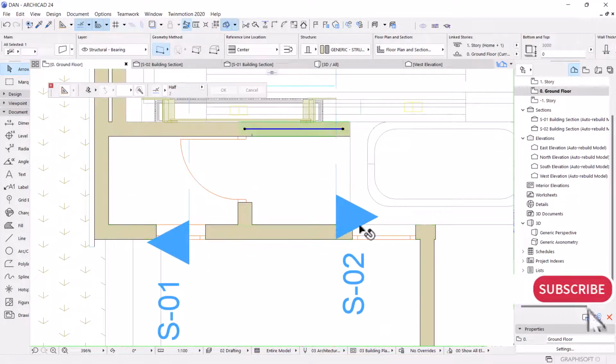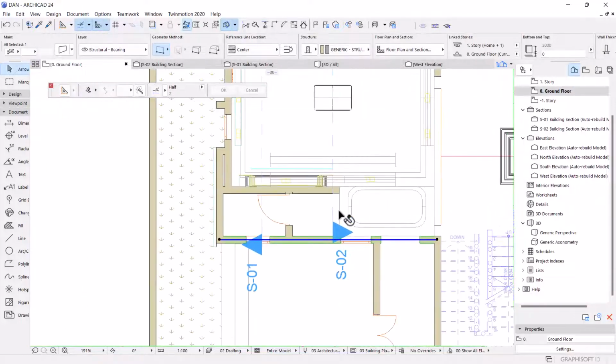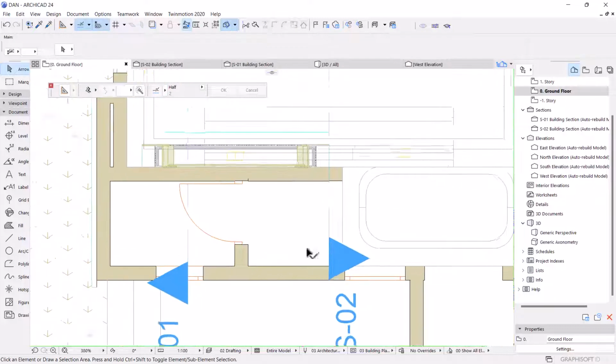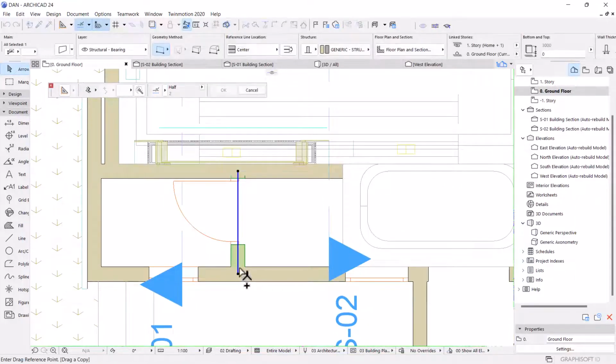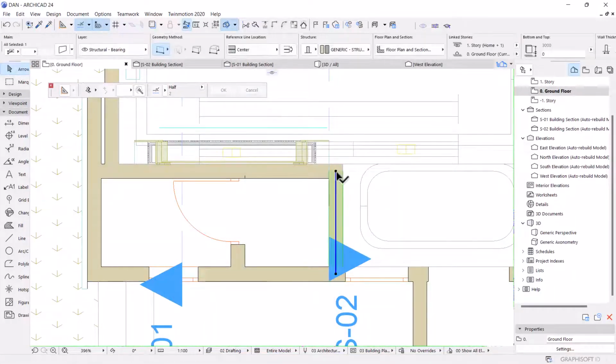So this one, let me just cut. Can I cut it? I did not have a wall here, but I think I was supposed to have a wall here. It could look better that way. Let me copy this with Ctrl+Shift+D, so that we bring it here and we delete this door. Then I can shorten this wall to the same length as this.